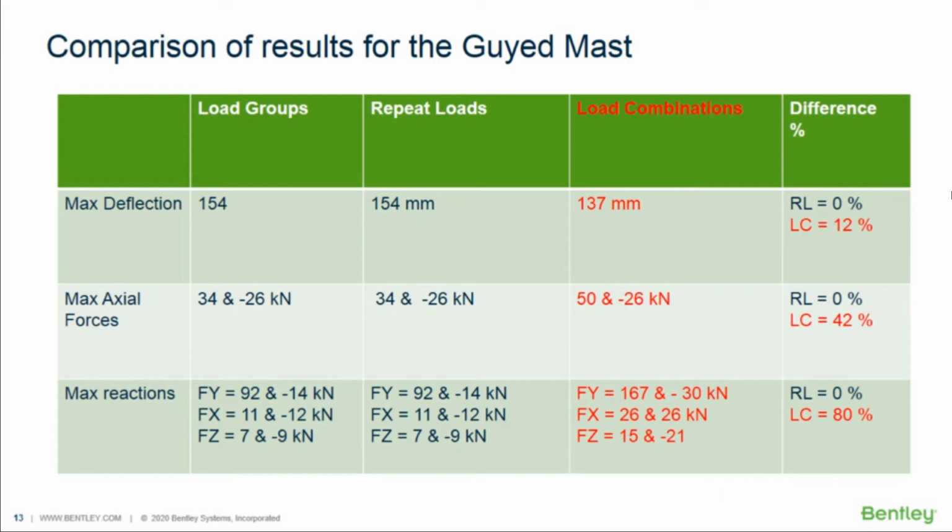So with this small example, you notice that you should not use the load combination command for structures having cable members, member tension, nonlinear analysis, P-delta analysis, spring compression, spring tension, etc., which I already explained in my previous tech talk in April on applying load groups.